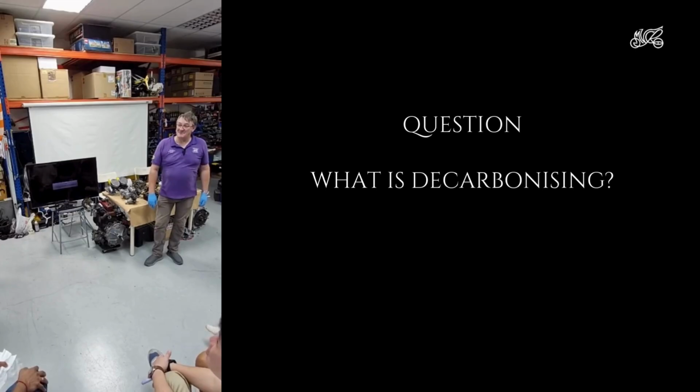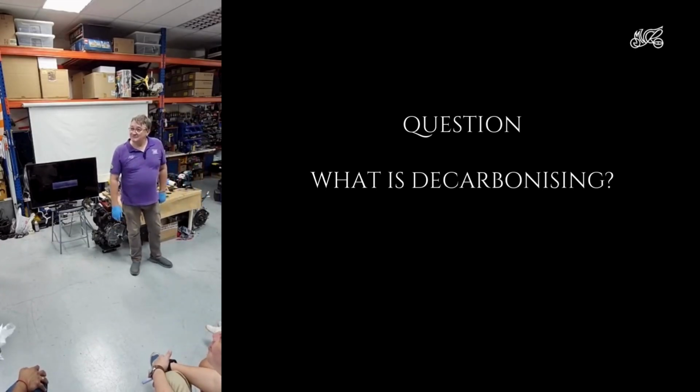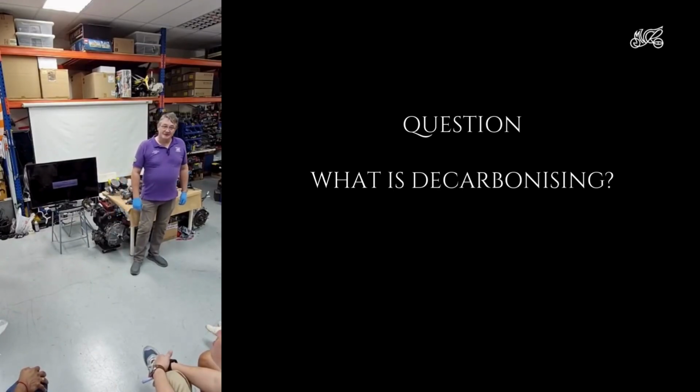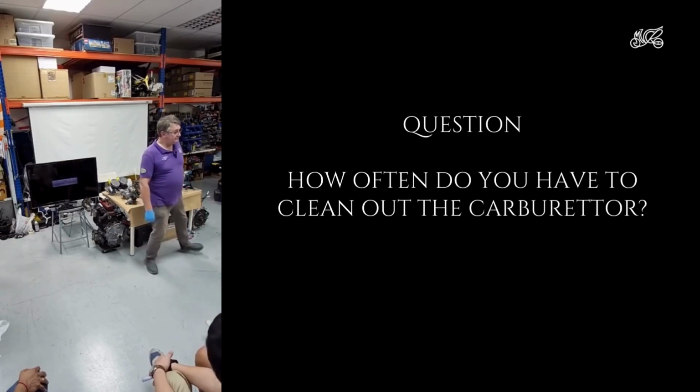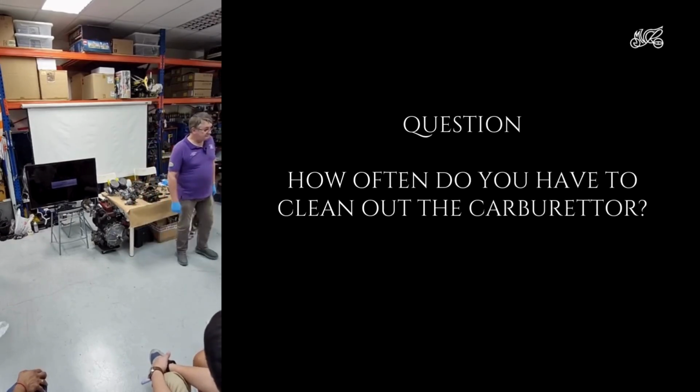Time up. Just another point. Spark plugs, right? Also can cause power loss. Yeah. So done this before. Just clean up the spark plugs and fire up straight away. So it can be as simple as that. And one question: how often do you need to clean up the carburetor?